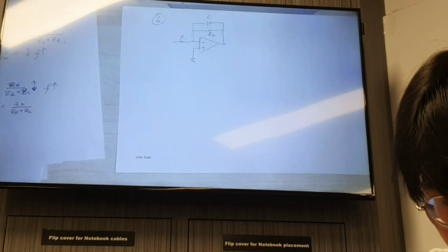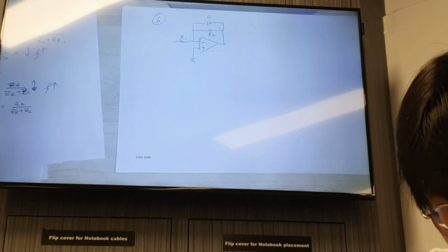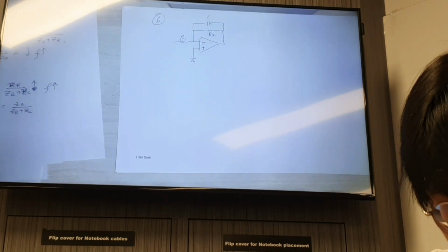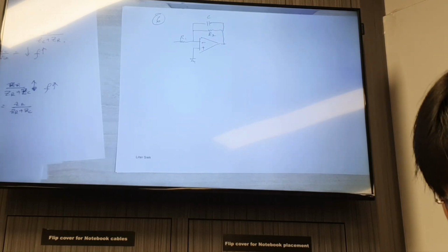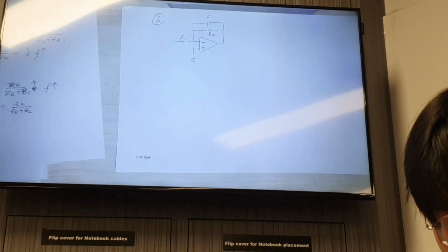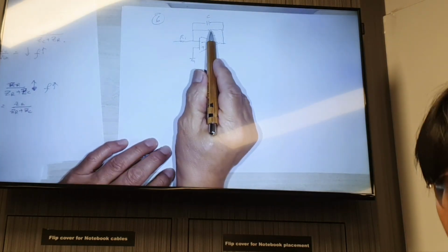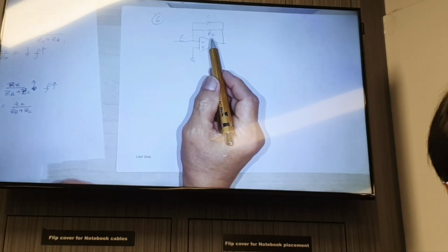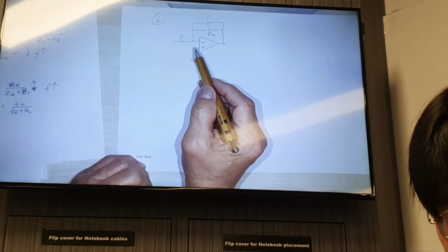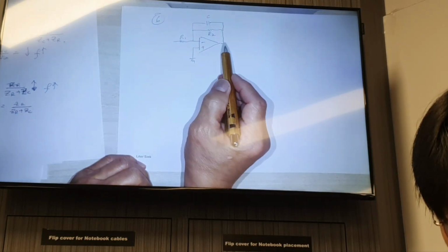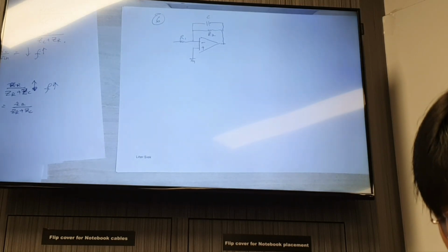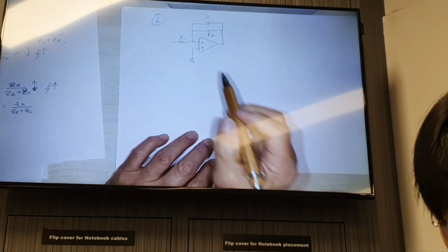Remember we did an op-amp when we introduced offset, and at the end we said that without the input, the output happens to be negative, and therefore the output will swing towards the negative and clip at the negative, and so on. So same thing. Here, the idea is to limit the offset going through the gain so that the output will not be stuck at VDD or ground. And therefore now you look at this.